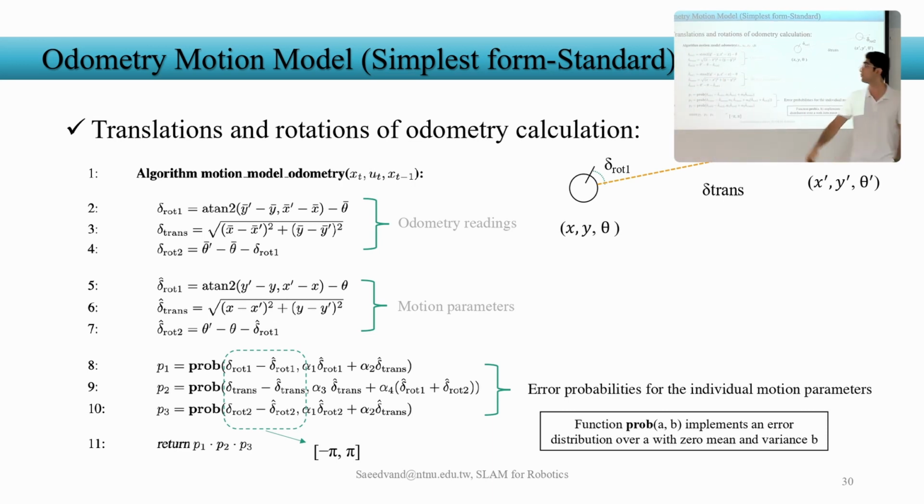Now if the robot moves like a curve, based on odometry reading, what do we need to do? That's one discretization approach that we can do, but it still has error, because however small we make the steps, we still have error and we're losing something. Like with an integral that we discretize, we're losing something there. So the same problem will happen here.